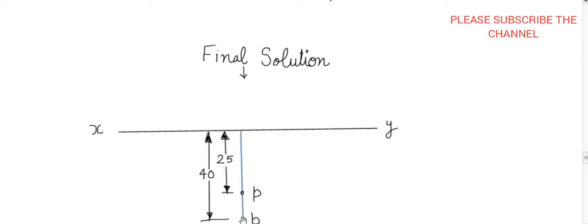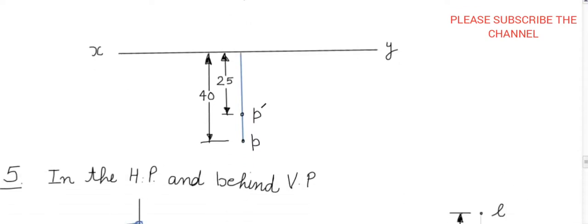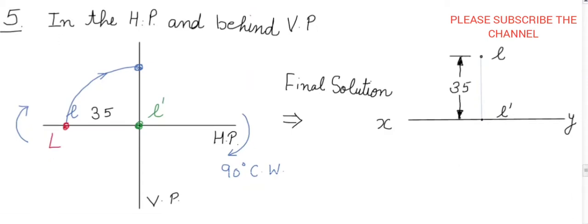Same case as in the second quadrant, but this time the projections are drawn below the reference line. In the second quadrant, the projections are drawn above the reference line XY. Similar case. So this one is your front view, and this one is the top view. Very easy. So now move to the fifth case, which is rarely asked in exams. The point is lying in the HP.